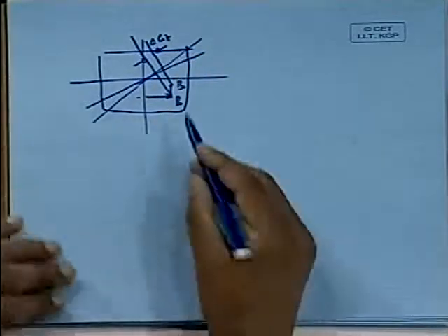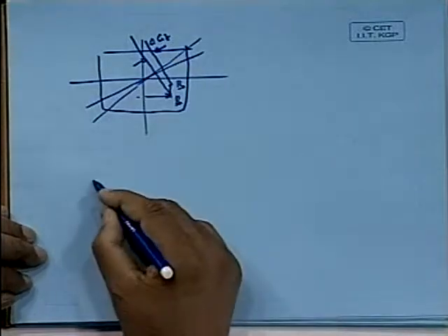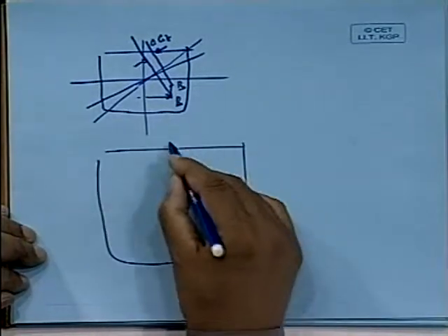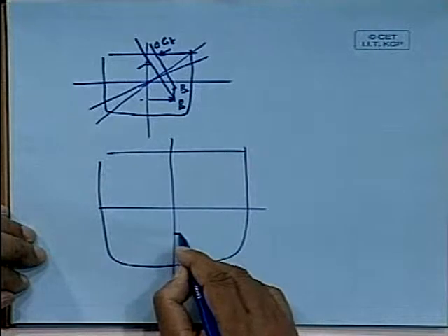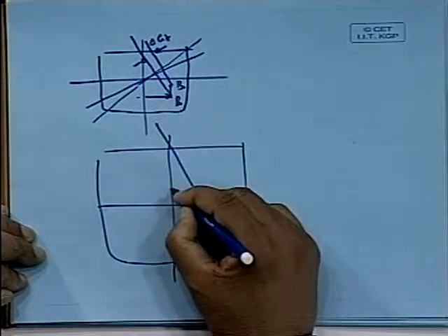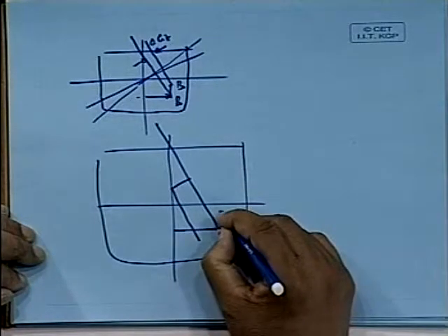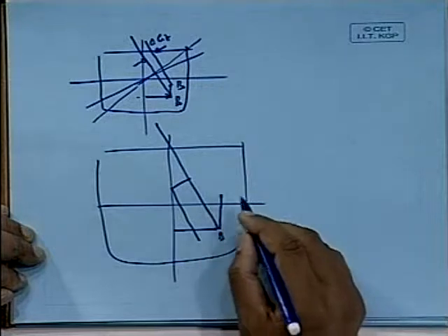See, this center of buoyancy, okay, we'll write it the other way around. Just one case, if the center of buoyancy has just moved here, then my force is like this, G is like this, my GZ is this. But if it moves also up, I am just drawing an exaggerated diagram, it will never move so much.